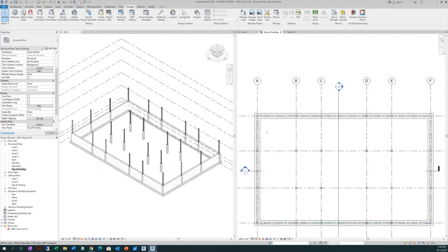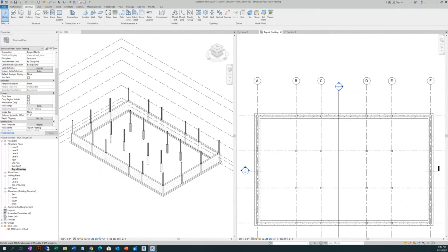Correct. Now let's go place here the isolated footing, in order to support these pedestals or pilasters. Okay, let's go here in the Structural tab and look for Isolated. No structural foundation family is loaded into the program. Would you like to load one?